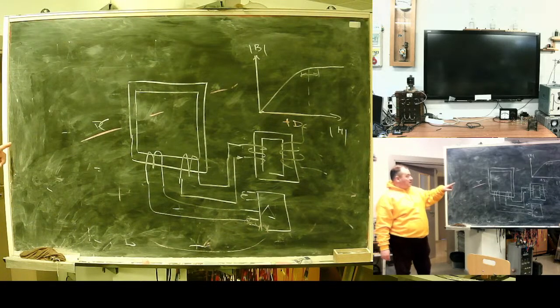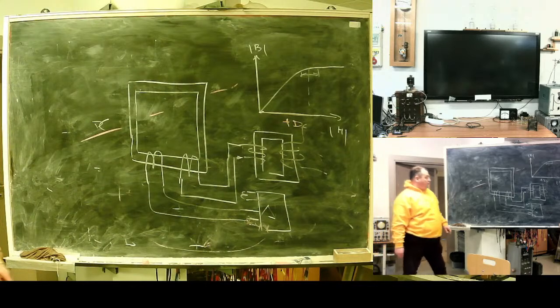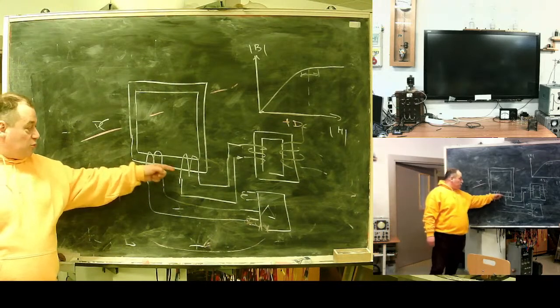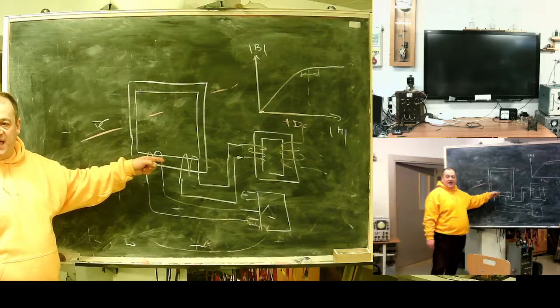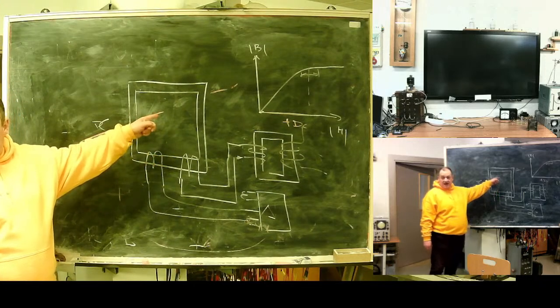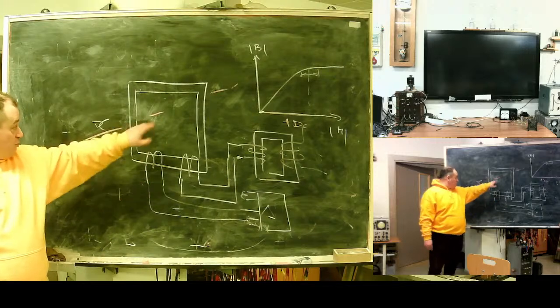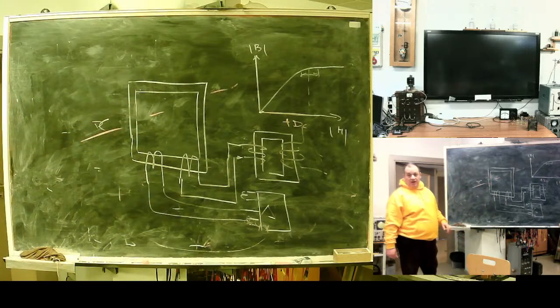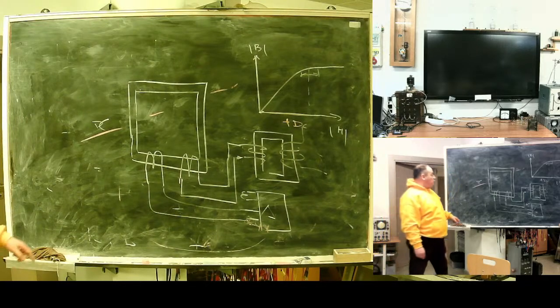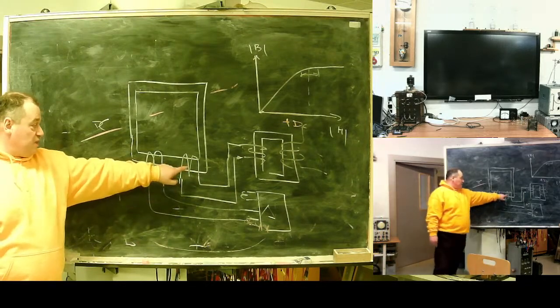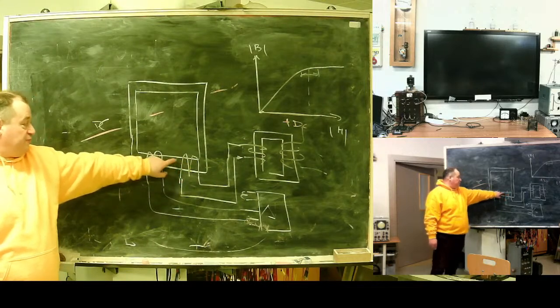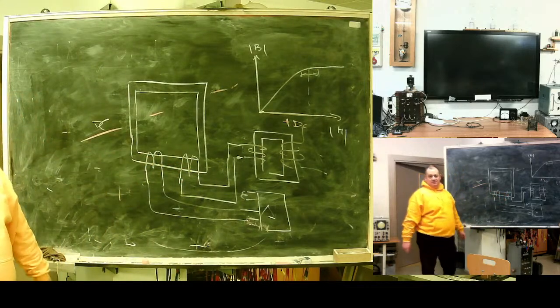If the magnetic material is selected well, you will have an area which is linear, where the transformer ratio decays with the DC current. The idea is that this core is saturatable, and the higher the DC current, the deeper the saturation, and less current will be transformed from the sending coil to the receiving.